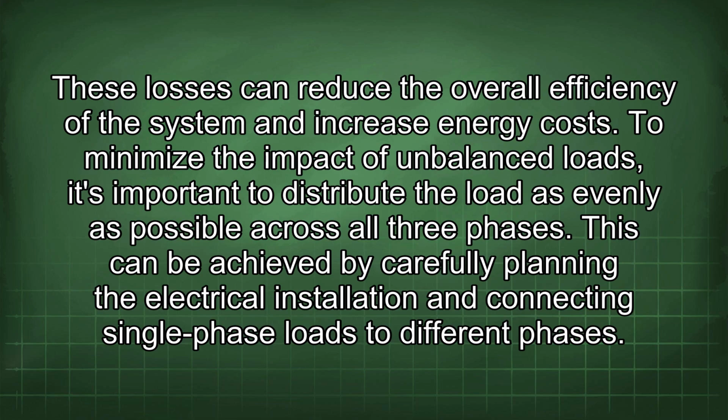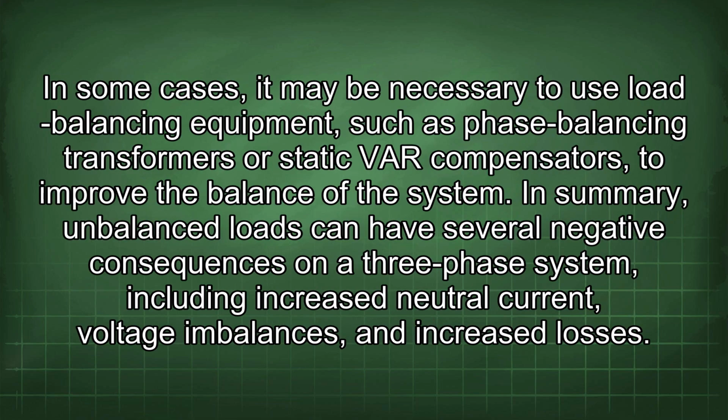To minimize the impact of unbalanced loads, it's important to distribute the load as evenly as possible across all three phases. This can be achieved by carefully planning the electrical installation and connecting single-phase loads to different phases. In some cases, it may be necessary to use load balancing equipment, such as phase balancing transformers or static VAR compensators, to improve the balance of the system.